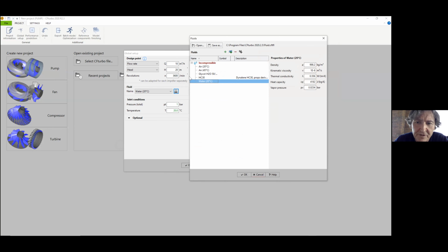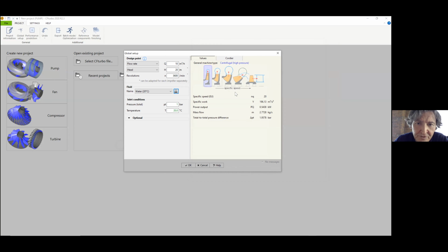On the right side we have a sketch of the specific speed, and you would see we are in an allowable range. Specific speed is about 20, and we could build a single stage machine. However, for this typical application we have a limitation in the outer diameter. This is what I mentioned before as the reason why we build multi-stage pumps. The radial extension is limited to 50 millimeters. So that's why we want to go for multi-stage, and we have chosen this example.